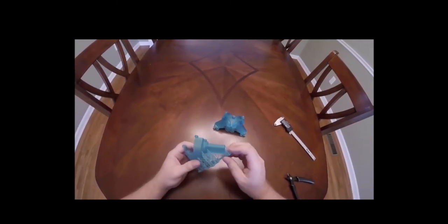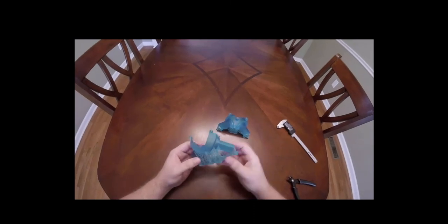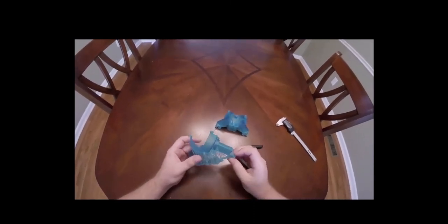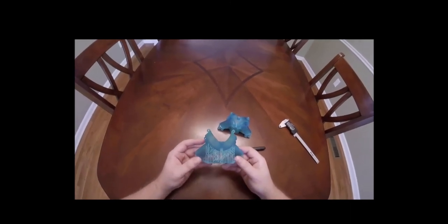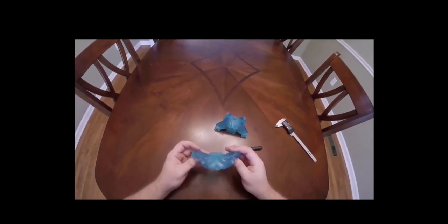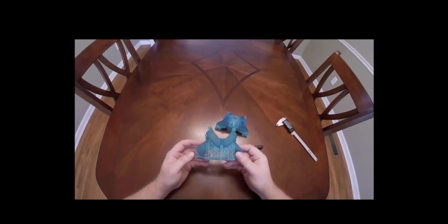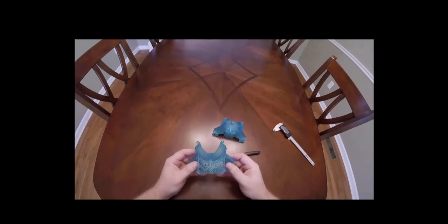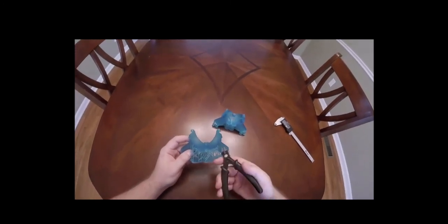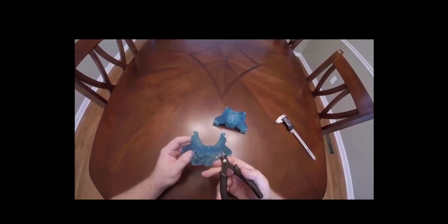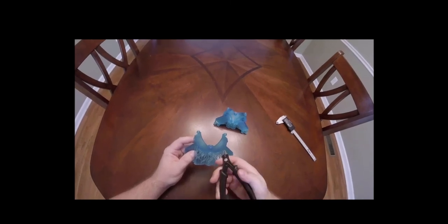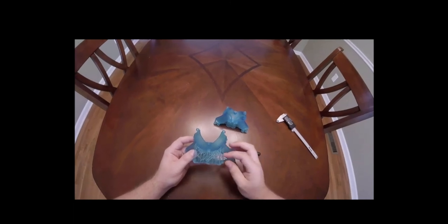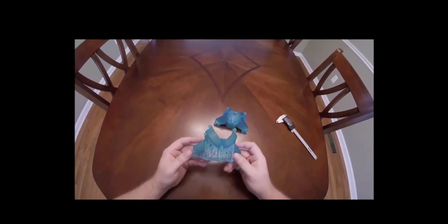So you should think about which way you're pulling on the supports, and maybe remove supports manually with some clippers in places that could end up dragging across the part and scratching it up. If I'm doing something really delicate and small, like a mini figurine or a character of some sort, I might go in and clip the supports kind of long, out here in this area, and then come back with an X-Acto knife later and clean them all up really nicely. This really just depends on the type of model and how large it is.